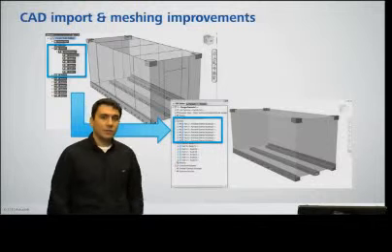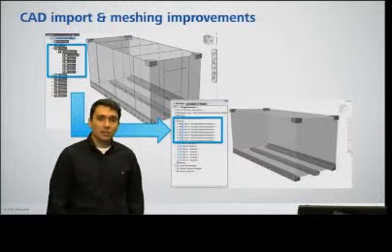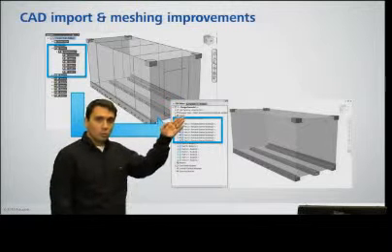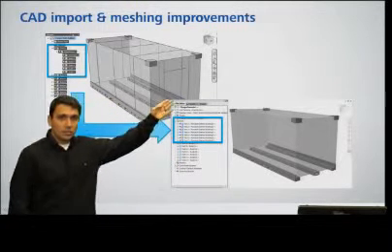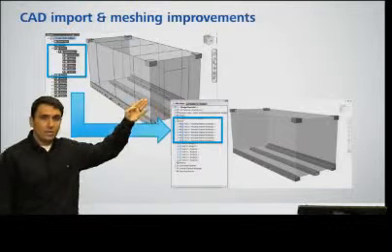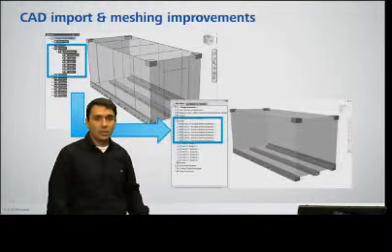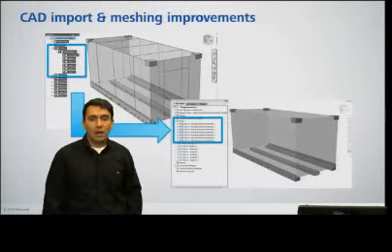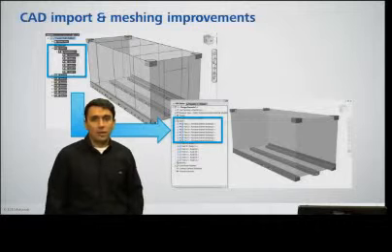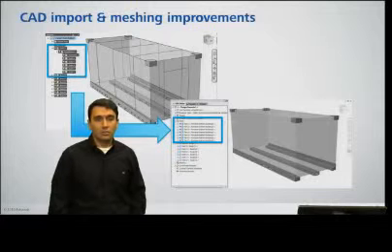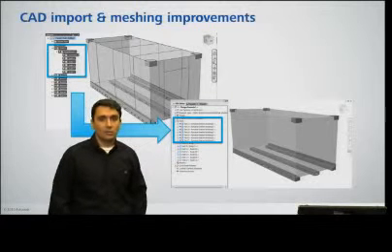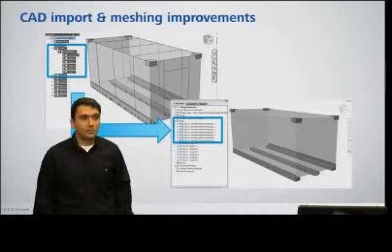This improvement has a secondary benefit such that when they're trying to do parametric design studies, those surface objects, such as the ones that we've shown here in transparency, will come into Simulation Mechanical every time after a geometry update, and the parametric design studies will run successfully and give them the new geometry and the new results based on the parameters that the user sets.